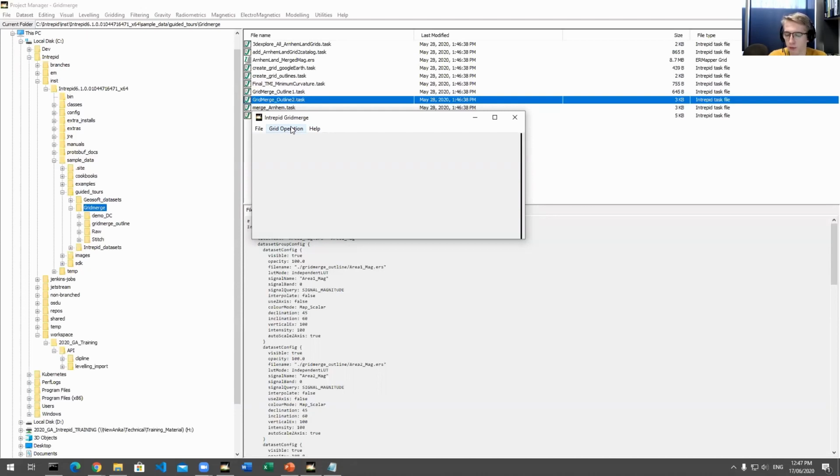It's only a very rough, well, I won't say rough. It's a fit on the overlaps, so the overlaps line up, but obviously there's going to be differences between the two grids at this point still, and that's where the surface adjust comes in to minimize those. So the DC shift is going to work out between any pair of grids what the overlap pixels are, and then work out the least squares DC shift to the whole lot. It'll apply it to the whole grid and bring that all up to value, and apply a single correction to it.